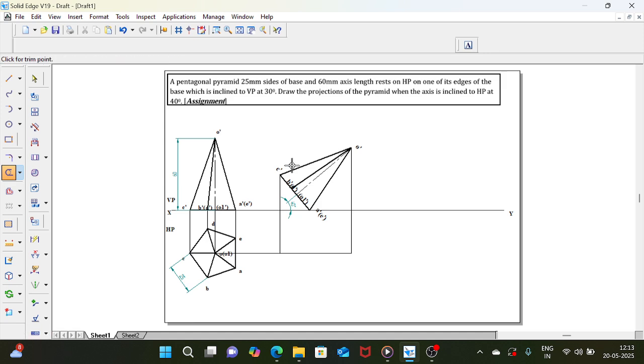Trim the unwanted line and mark that O and C immediately. Don't create confusion by leaving it to the end to join all the lines. Mark all the points. And then draw the A projection line. Here you see the A projection line is here. A and A intersect here. So after getting the A point, trim the unwanted line and mark this as A.